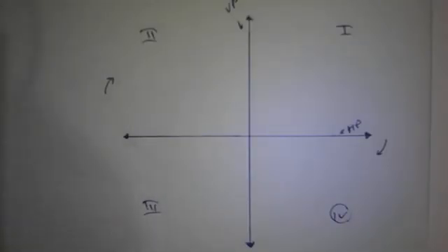Point A, in which the front view and the top view both are above the XY line. We know that when the front view is above the XY line, it can be in the first or second quadrant. But by determining the top view, we can find that it is in the second quadrant, as the HP plane gets rotated, so it can be above the XY line. So that's why it is above the XY line. So it is the second.